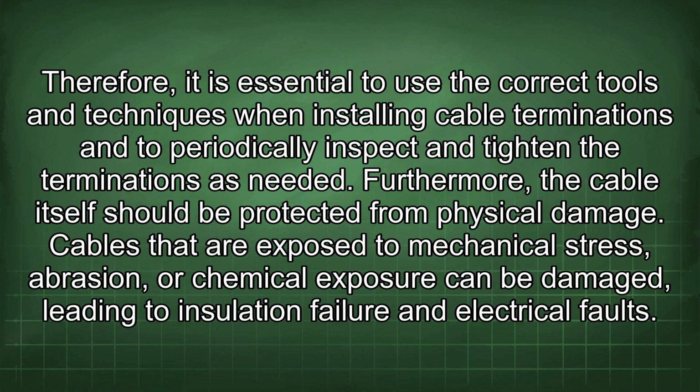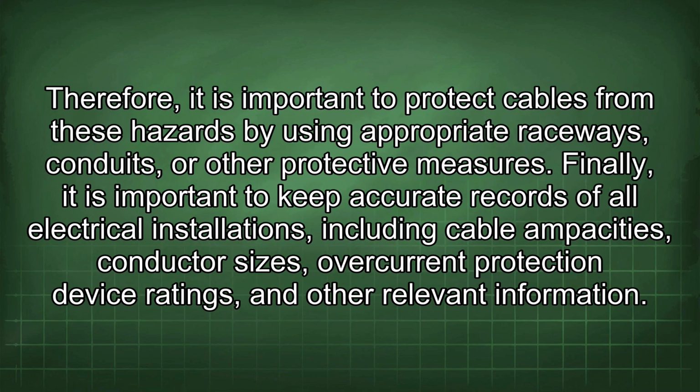Furthermore, the cable itself should be protected from physical damage. Cables that are exposed to mechanical stress, abrasion, or chemical exposure can be damaged, leading to insulation failure and electrical faults. Therefore, it is important to protect cables from these hazards by using appropriate raceways, conduits, or other protective measures.